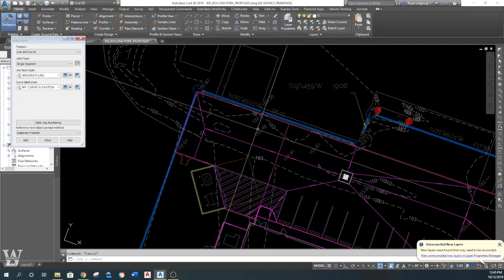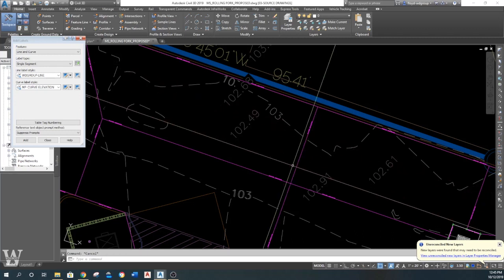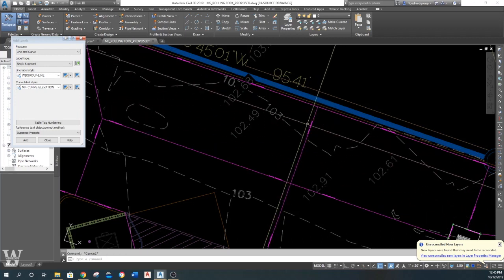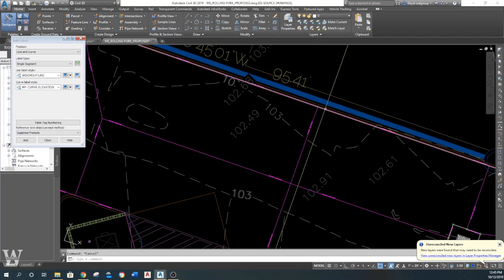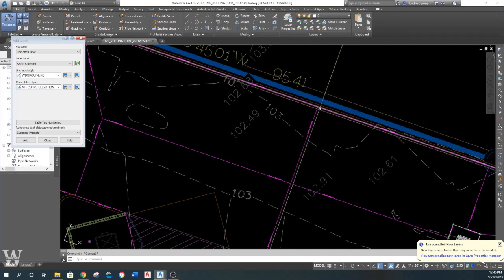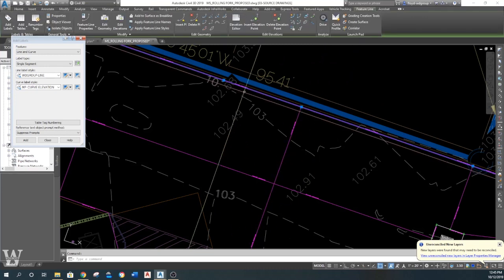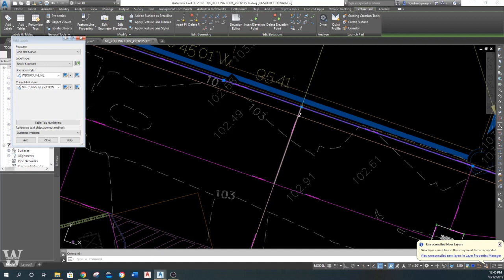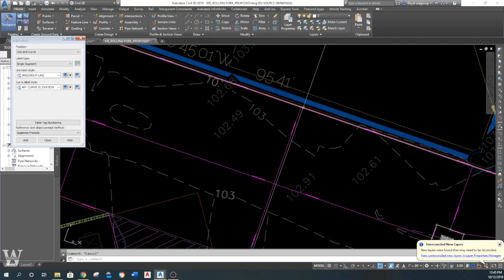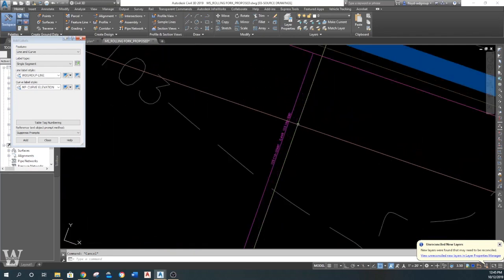By doing it the way I just did it right there, okay, I didn't assign that an elevation. I picked it on a line that didn't have a PI point right there. Then I put a PI point right there, and I let it be whatever. I don't know what elevation it picked up. I don't really care, because when I put that PI point in and go from here to here, it keeps the same grade slope I had, and therefore I didn't really have to check the elevation. I could just go click, click, click, and have one.